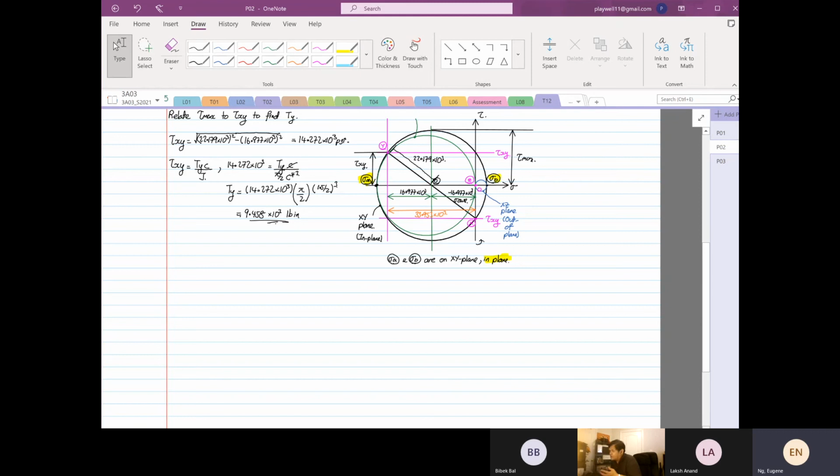But when you apply it, it's so straightforward, especially when you understand the 3D Mohr circle, what is in plane, out of plane, why you have to construct the 3D Mohr circle to identify stress A and stress B, your principal stresses. Any questions so far? Okay, I don't hear anything.